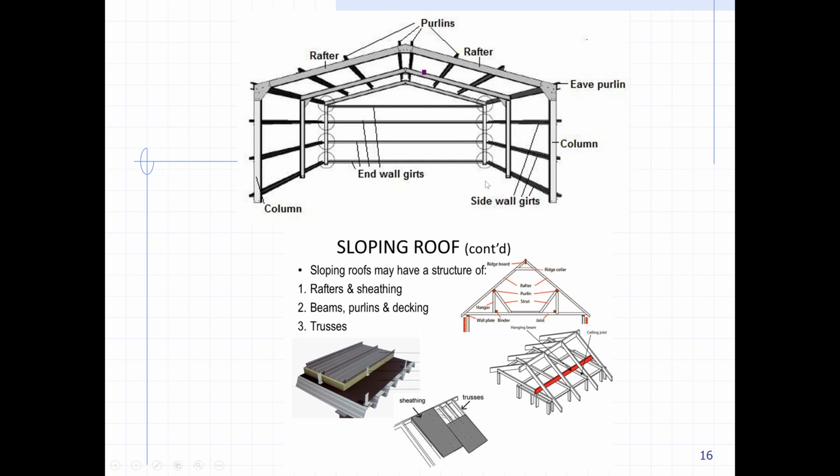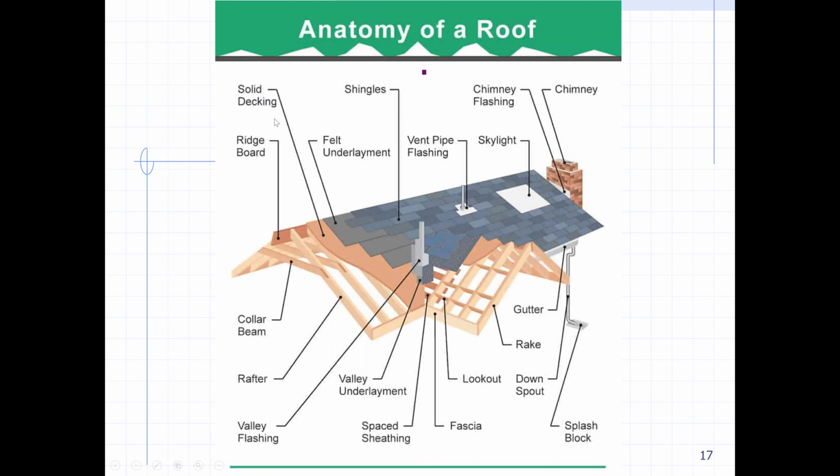And then, in the sheathing, this we call sheathing above the purlins. On the truss we put sheathing that will cover the roof. Here also is a solid decking; solid decking is sheathing actually. And then for waterproofing we put a felt layer, and then this is again rafters. And at the top, those tiles that people can see in different colors, maybe red or pink or many colors people use, we call shingles, shingles.